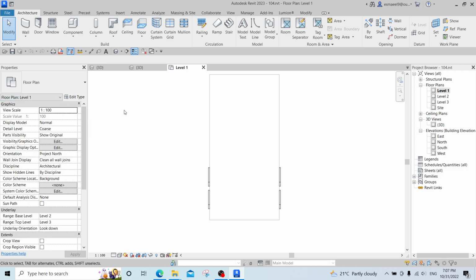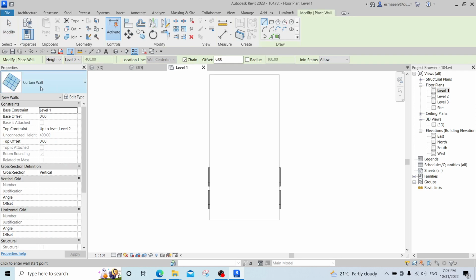And the properties, we said, is the information about all the families, about all the things you are doing. For example, if I click WA for wall, these properties will open the properties of the wall I'm going to model. This options line is the same as the properties. It's telling me its height, and it's until level 2, the same information from level 1 to level 2.